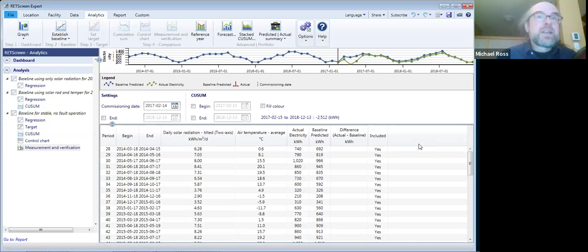Yes, but it is complicated a bit. Now, if you think back to the power curve for a wind turbine, it's highly nonlinear, right? It has zero at low wind speeds, and then it ramps up with something like the square or the cube of the wind speed. I mean, in theory, it's the cube, but in reality, it doesn't necessarily follow a cube. And then it flattens out as it approaches the nominal power of the wind turbine. So that's a highly specialized function. And if you're trying to fit data points to that function, it's going to be challenging.